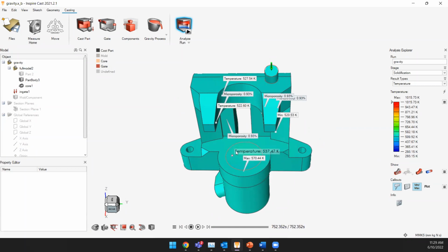And this is a big hole. If you say, that's okay, I will create the mold with material over here, then you have to machine that particular material out. That's an additional step for post-processing. In order to avoid both machining for post-processing and wastage of material, we add cores.